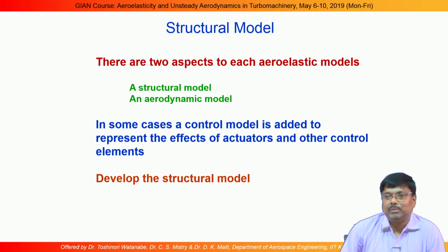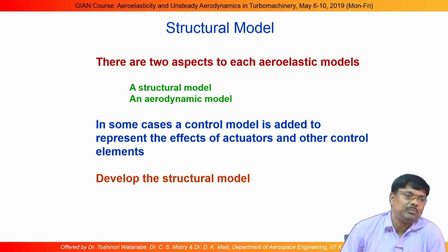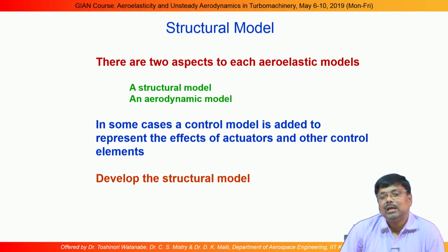But in addition to the structural stiffness calculation, we have to consider these two different forces, thermal forces and centrifugal forces, to get the total stiffness of the structure, which we call the effective total stiffness, playing a role in the aeroelastic model.